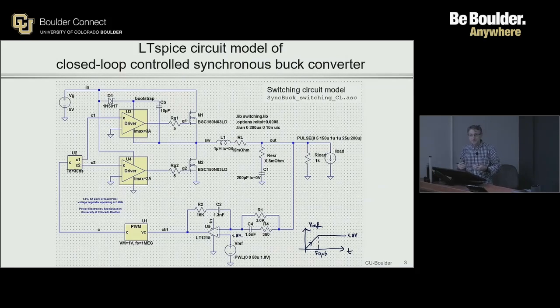That often results in transients that are not desirable. You may have an overshoot in the output voltage that would be prohibited by the nature of the load. You may damage the load in the process and so on. So this particular ramp up gradually of the output voltage is commonly referred to as soft start. So this is one version of what is called soft start technique, implemented here through actually just gradually ramping up the reference from 0 to the final value of 1.8 volts.